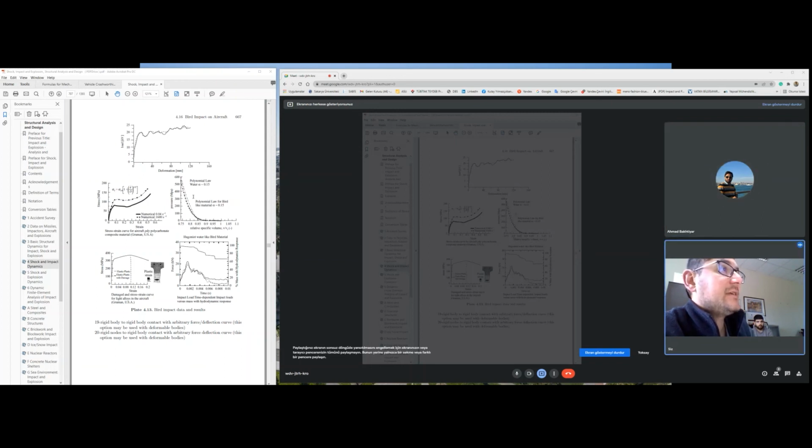Yes. You can apply it, change it, for example, instead of bird impact. No, I'm talking about some ways that you can contribute to our study. For example, here, stress strain. Okay, we look at here. It is using strain rate, and this is Cowper-Symonds. This is using the Cowper-Symonds parameter again. And as I told you here, relative specific volume.